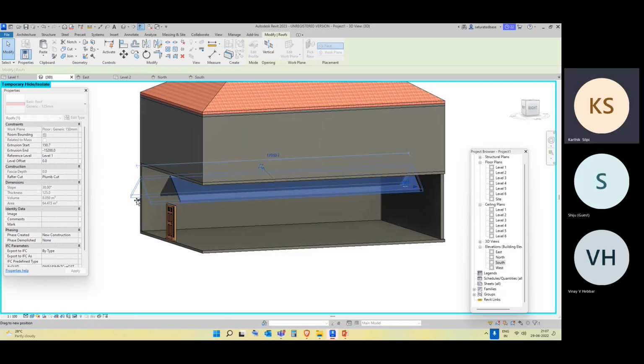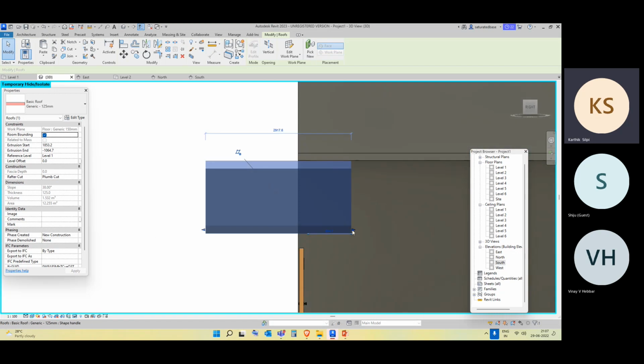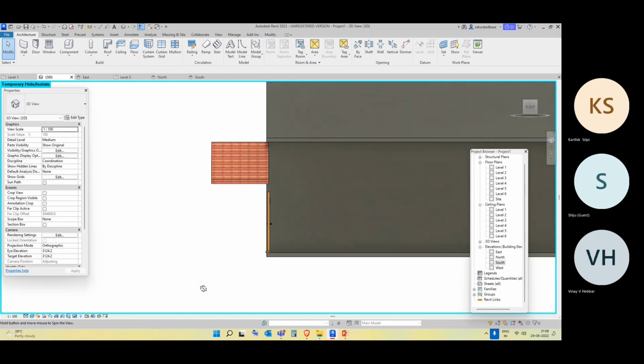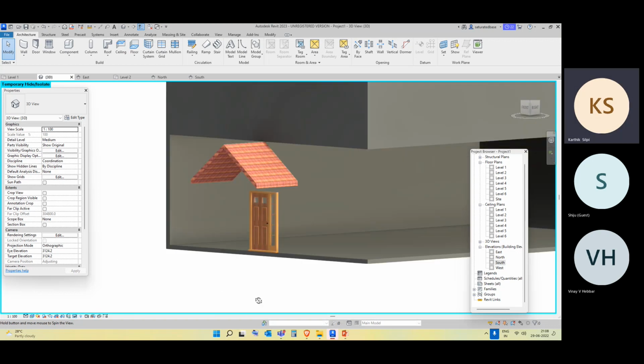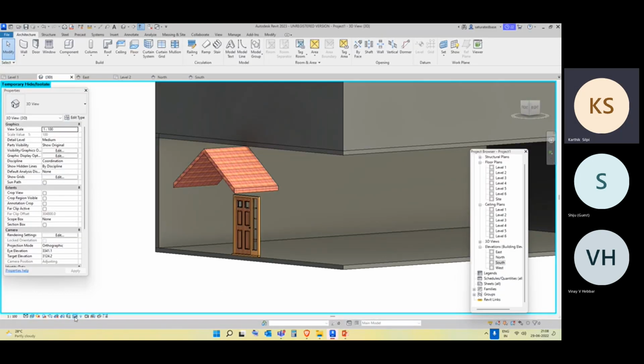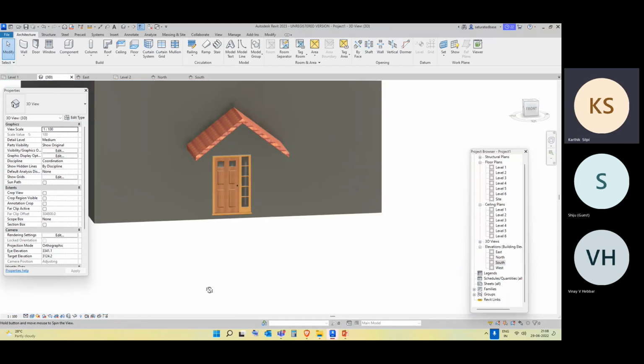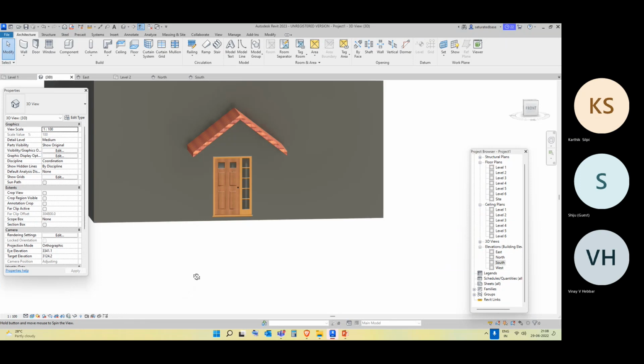You can just scroll it in both the directions until wherever you want. Let's say I am going to view this in right view. You can see this is where our wall is going to start. So the distance is, let's say, 2000. I can just type 2000 and stretch it. Now after moving, I want to get my walls back. Just hit the spectacles again. Go for reset temporary. In that way, I am going to have my roof.